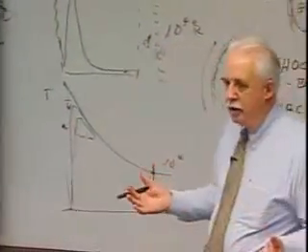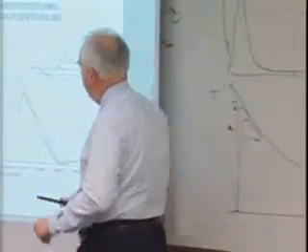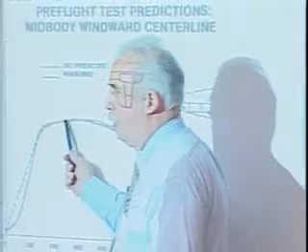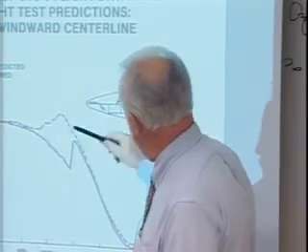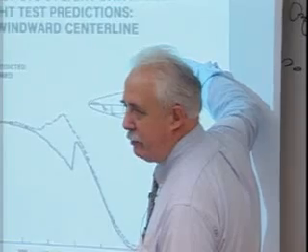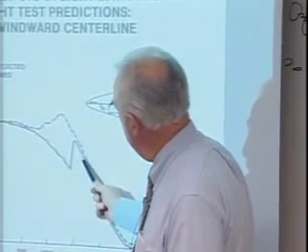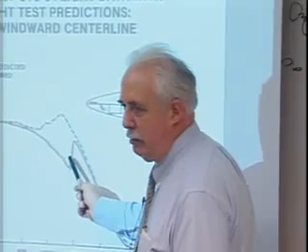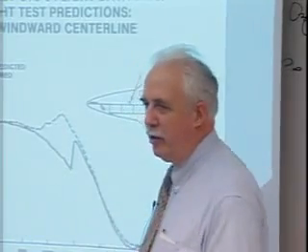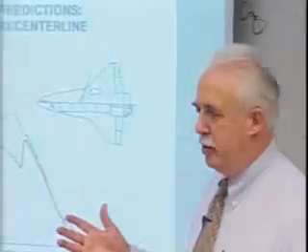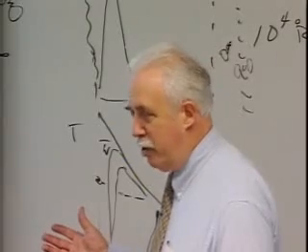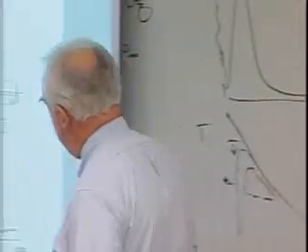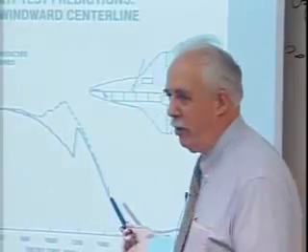All right, here's something you might see in a journal. Right where we wanted it, and that's where we had the most confidence too. We got away from the subsonic, supersonic condition. We were into a marching solution. That's as good as we could do it in those days. We knew that transition was going to be later than what we predicted, because wind tunnels are noisy. You've got walls, you've got all kinds of reflected noise, and wind tunnels are notoriously conservative relative to boundary layer transition. But amazingly, the turbulent heating correlated quite well.